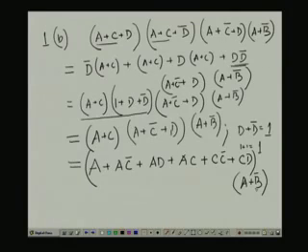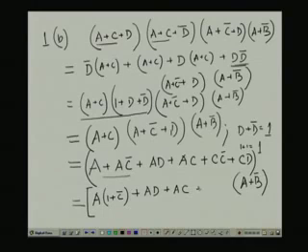Now this is a nice expression, and if I take two terms at a time, say A plus A C bar, from here if I take A common, then this becomes 1 plus C bar, and I keep all the other terms as they are: A D plus A C, plus C C bar becomes 0, plus C D, and then multiplied by A plus B bar.